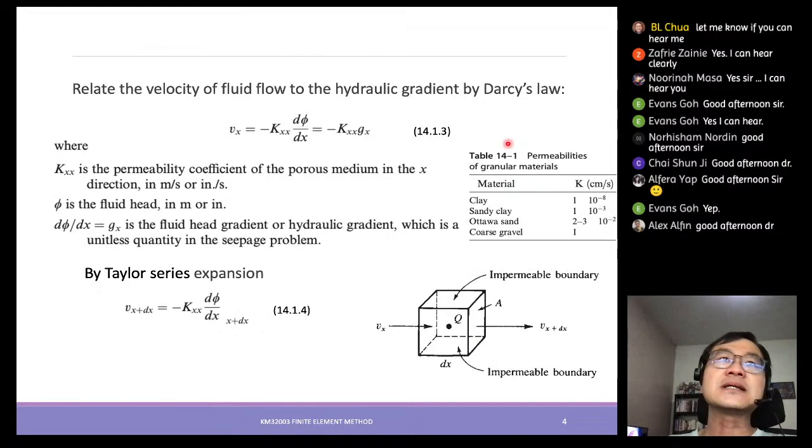Again, through this porous medium, now we will start to define how the fluid will flow through it. What is the velocity related to the fluid flow when it goes through a certain porous medium? You can estimate it through some theory. So the famous Darcy's law that you have learned in fluid mechanics comes in. You have V equals minus K d psi over dx.